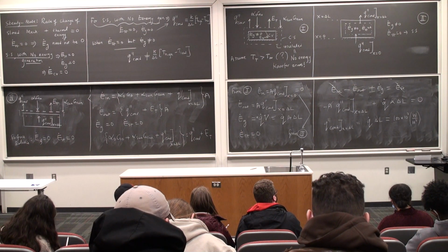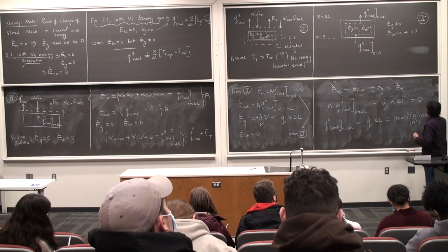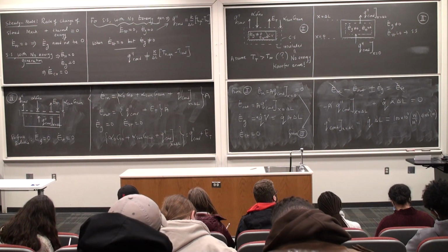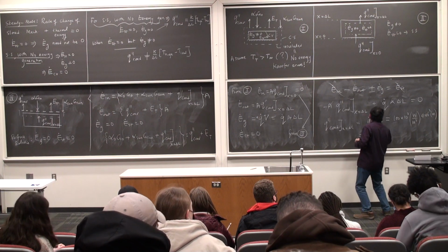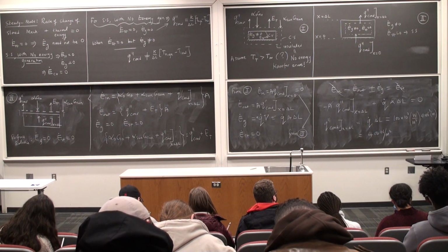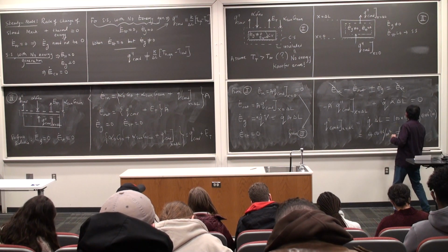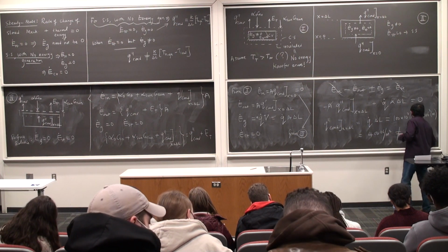Delta L was 4 millimeters, convert everything into meters. So 4 times 10 to the power minus 3 meters, or this quantity is just 400 watts per meter square, I'm sorry, it's a flux. And this is not equal to q double prime conduction at x equal to 0.